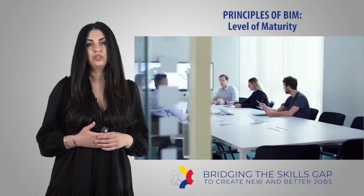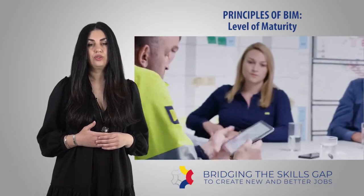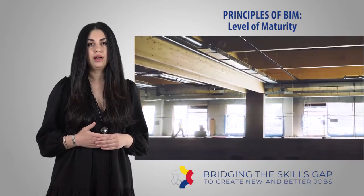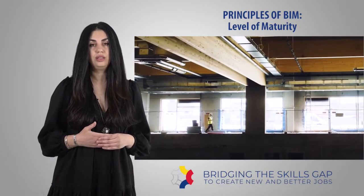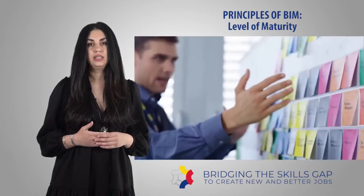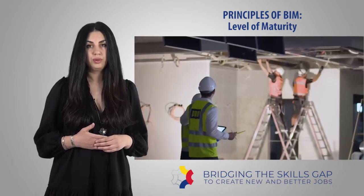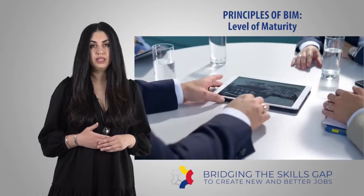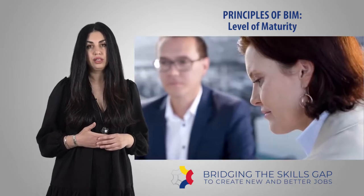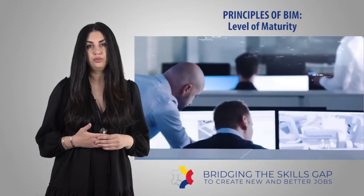Multiple associations, such as buildingSMART, governments, and industry representatives, are working on making BIM more standardized and technology ready. The IFC format, for example, developed to ensure open BIM by buildingSMART and supported by all countries, will become the international standard format for BIM software. IFC has been in development since the mid-90s. It was created to ensure interoperability. Today, it's a format that is not editable, but it's being used to exchange BIM data. Currently, IFC files can't be modified or saved, but hopefully it will soon be updated.